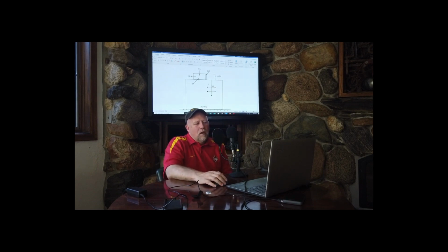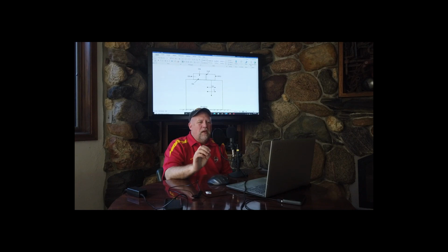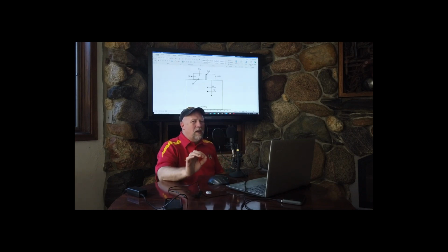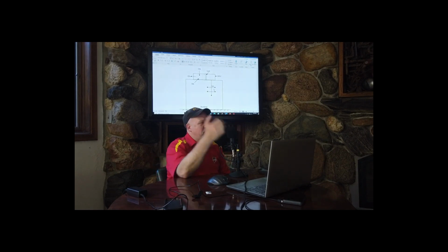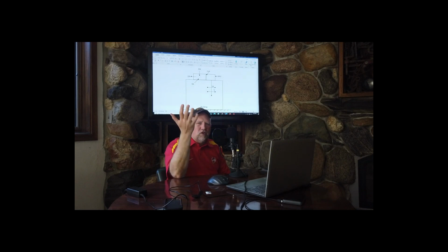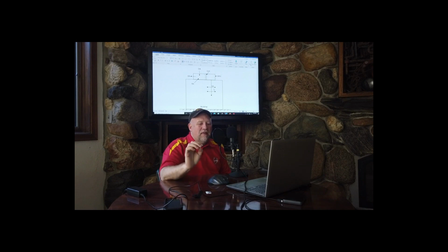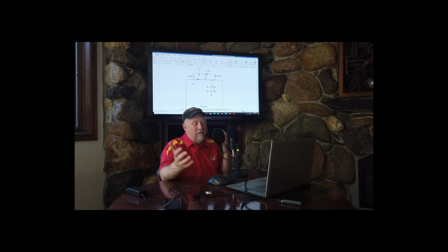Also, the device that we use to control whether or not we need cool air, and how much of it, is just a thermostat that's going to be sitting on the wall. Think of your house, think of your car, think of an office space. You've got a thermostat on the wall. It's going to measure the temperature and then decide, hey, do we need air conditioning or not? And if we do, we're going to dump some cool air into the room. That sensor is a dry bulb sensor. We do not have moisture sensors in each room. And here's why. It's just a practical thing.